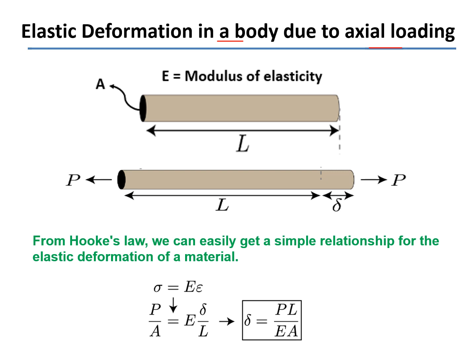Now you see this diagram. We have a bar of length L, A is the area, and E is the modulus of elasticity of that material. And in this bar or rod, we have a load P in the axial direction. So this is the axial loading. And now due to that axial loading, delta is the elongation. So that we have to find out.